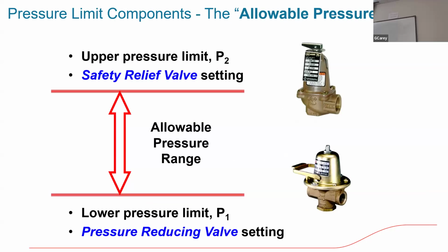So when we get into that allowable pressure range, what we're referring to is that we've got to set it because we've got to make sure the water's at the high point. We're circulating water, it had better be there to deliver cooled water or hot water. But then we have this safety relief valve that's there to protect the equipment, but I don't want it active. So here's my range. That's my allowable pressure range. I can let the pressure rise, just don't get to my relief valve setting so it opens and discharges. I want to prevent that.